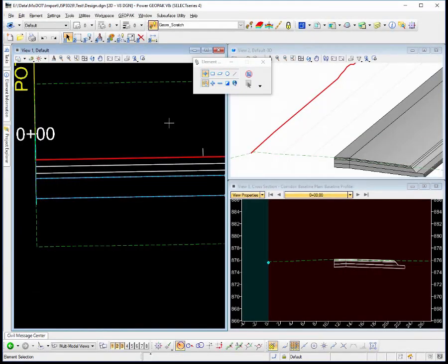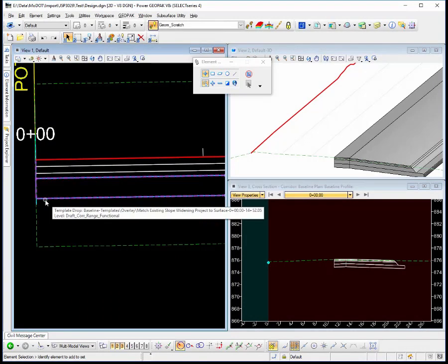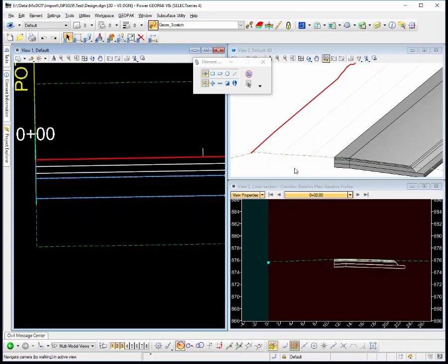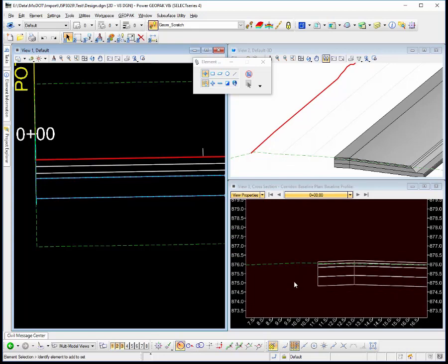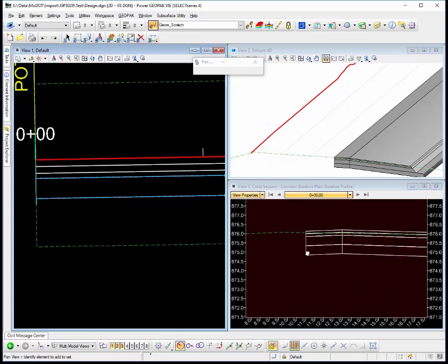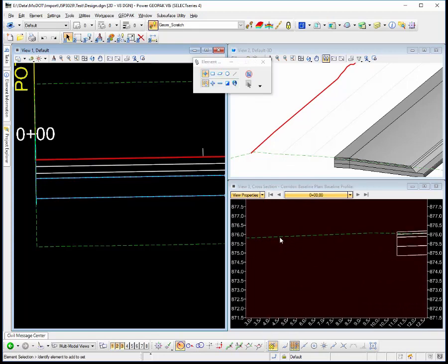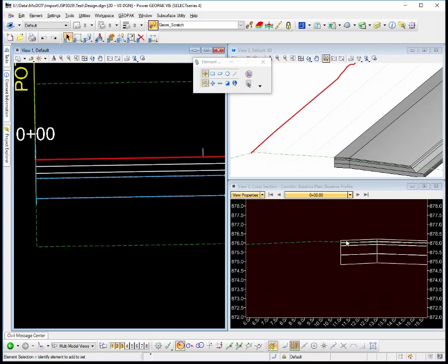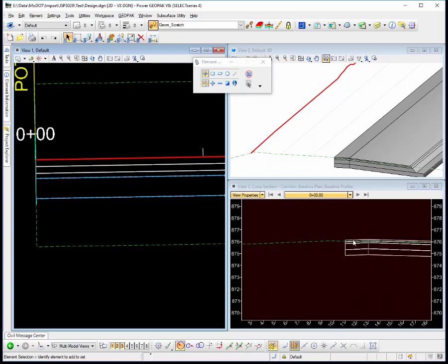And so what I did on my project is I simply changed to that particular template where I'm using the project to surface template, and I deleted my point controls, and you're going to see that my matching existing is going to exactly be following, if you can imagine, a point here at 4 feet and another one at 8 feet. It'll be projected through that plane and then match the existing based on those parameters.